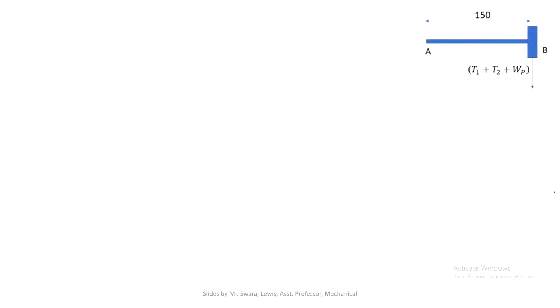So continuing the problem, we have to solve for the bending moment diagram to find the maximum bending. We got the torque, and we have to find the bending. Then we have a general equation for torque and bending together to find the diameter of the shaft. So how will we draw the bending moment diagram? Taking a moment at B.